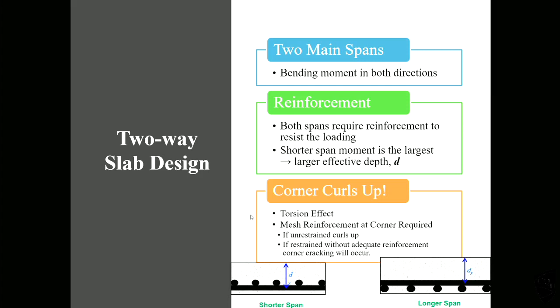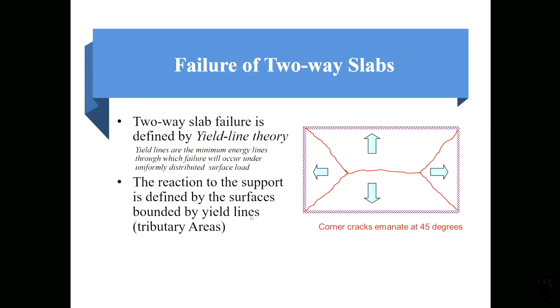So dx is large. The shorter span direction reinforcement will go on the bottom side of the layers. So dx is larger. Even though the calculation for both directions is almost identical, the effective depth is slightly different. Almost the same calculation, but the bending moment is different and the effective depth is also different. Otherwise it is almost a repeated calculation.